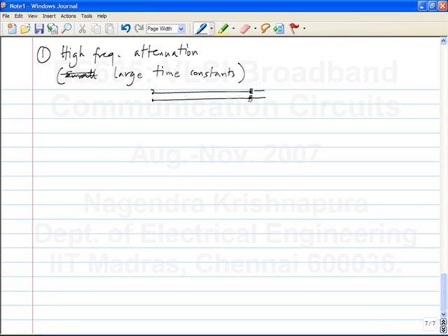Whenever you have an impedance discontinuity, you have a reflection. You know this from the basic transmission lines course. So for instance, if you have a uniform transmission line that is terminated by an open circuit, this has an impedance Z0, and on the other side it has infinity. If you send a pulse, what do you see? It will keep going back and forth. In a lossless transmission line, it will go back and forth forever. In a lossy transmission line, it will die out. But at least what you see won't be just a step. You will see some more things, some things like this.